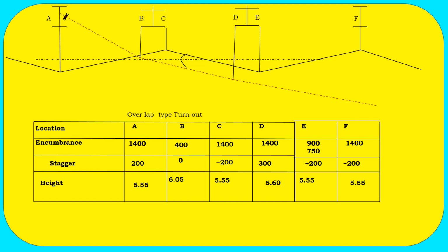The pantograph has two ends which are curved portions. First, on the bottom side of the curve, the turnout OHE will come when it is on the mainline. Then slowly the mainline OHE will also come on the pantograph horn, the curvature portion, and the turnout OHE will be on the pantograph. Slowly it will leave the mainline OHE because it is 5 cm above the mainline OHE.